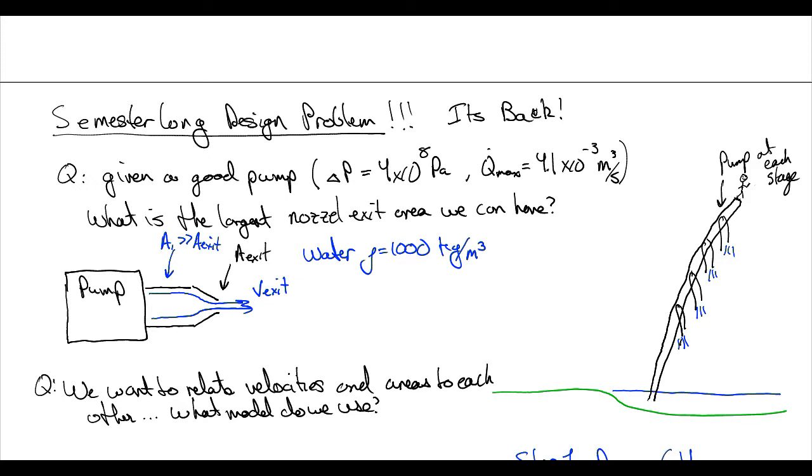But the force generated by each nozzle is equal to v squared rho times A, roughly speaking, or at least proportional to that. So if we can increase our area, we can increase our thrust. So we want to figure out what our largest area is because we'd like to have as much thrust as possible, right? Because we want to get this guy here, who is, in theory, me, as high as possible.